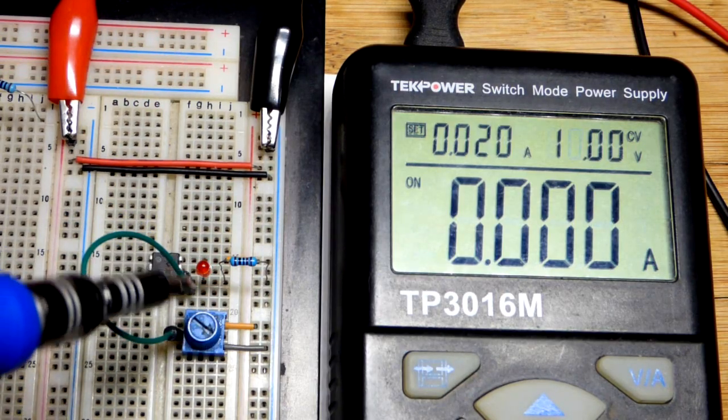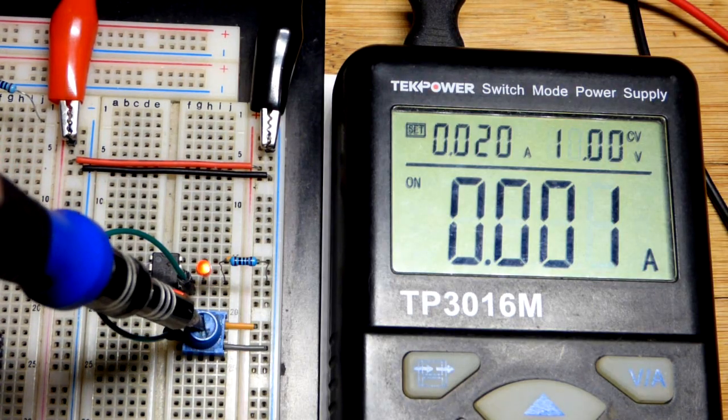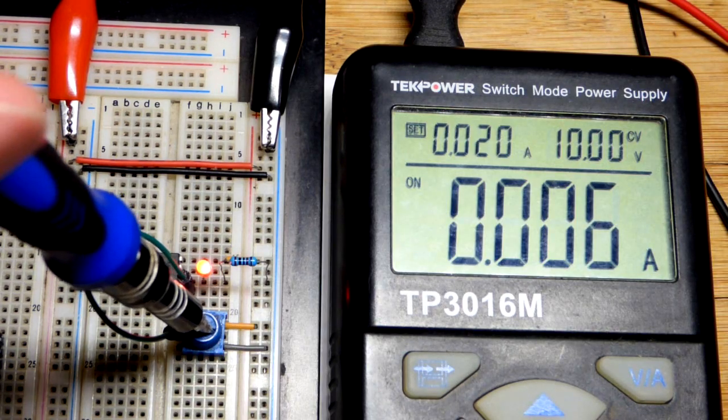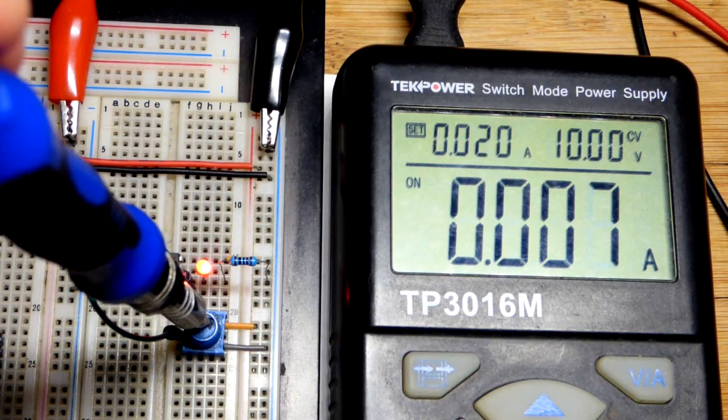But in any case, there we go. 0 volts, there is no current flowing. And then if I turn this up to about 1 volt, it'd be about 1 milliamp current. And then, you know, about 5 volts, 5 milliamps current, as we said before. There's an output limit to the op amp, though. We're not going to get to 10 milliamps of current.